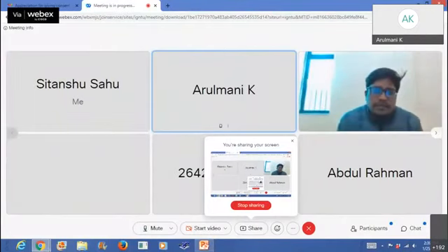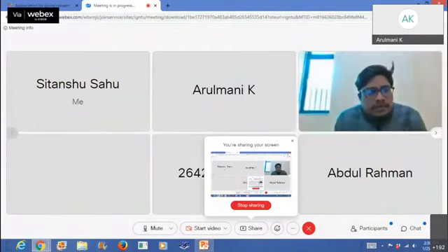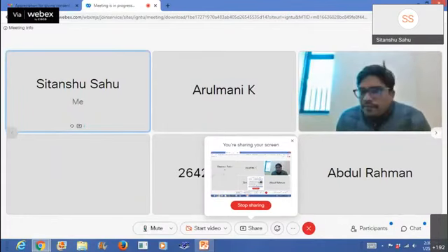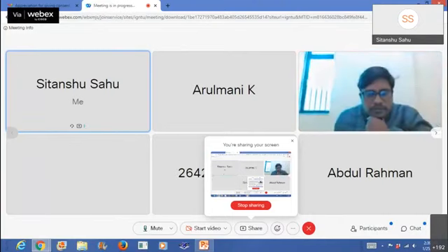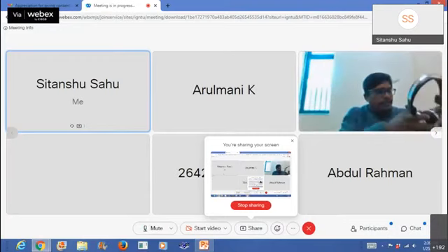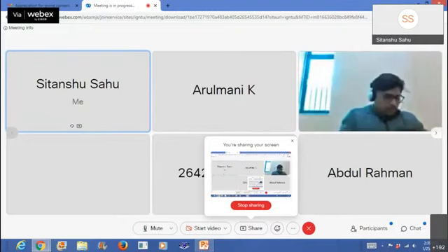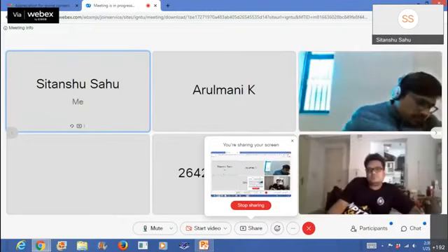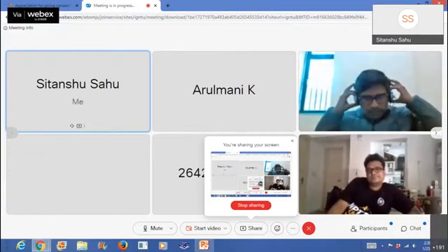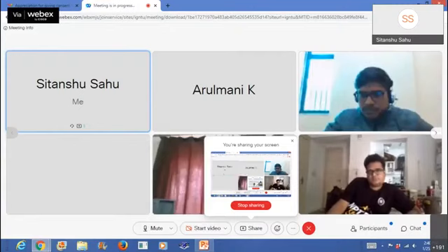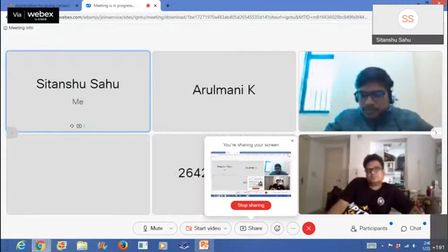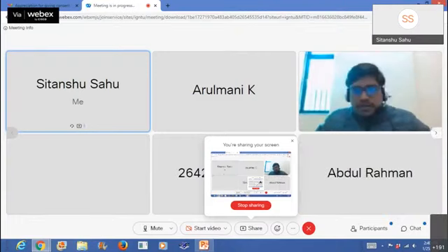The data is actually the speech. The data is a speech signal, and we cannot directly plot the speech signal to look at the variation present between the PD and the healthy ones. So what you do is try to extract or represent the speech signal in a different domain, which is called feature extraction. So we extract different features like the acoustic features: how the signal is varying and what the frequency variations are. Then we extract the features, and in the feature domain itself we see the distribution of the PD samples as well as the healthy ones.